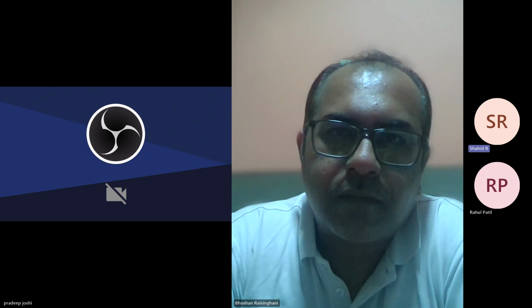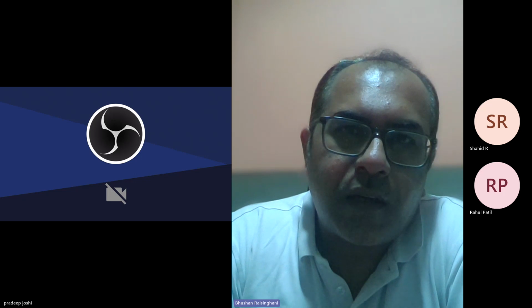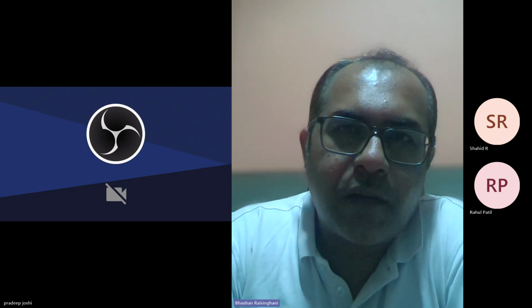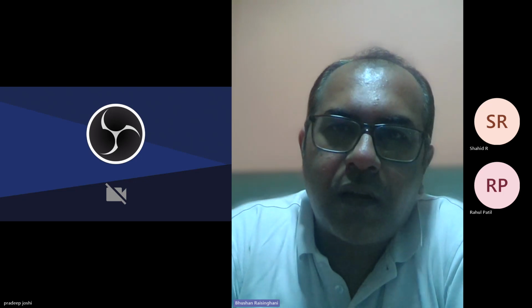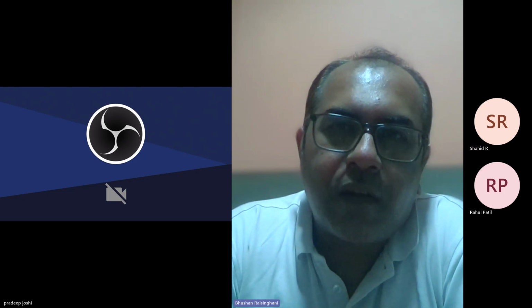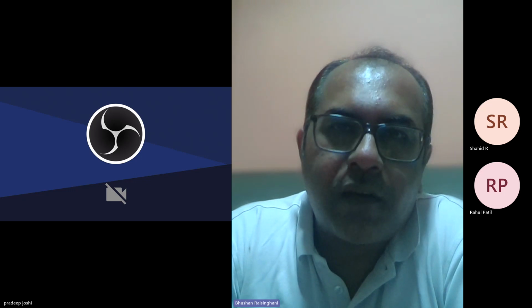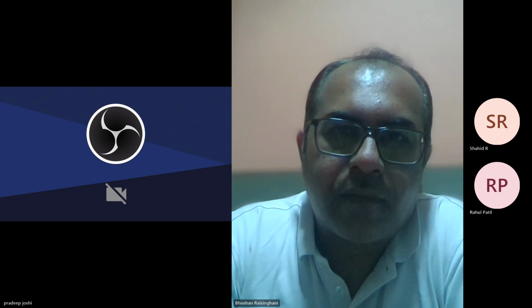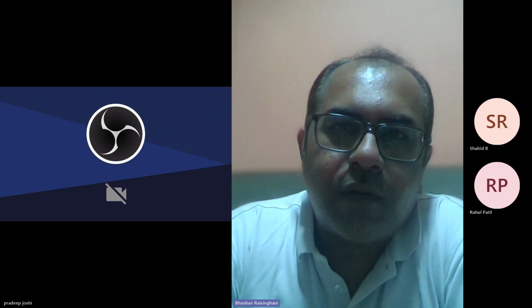No, we are not accounting for the bending. The drawback of modeling it as a membrane is that actual shear stresses generated during the backstay effect and in the floor system will not get modeled, so you will not design for it. That is the drawback if you don't model it as a thin shell.